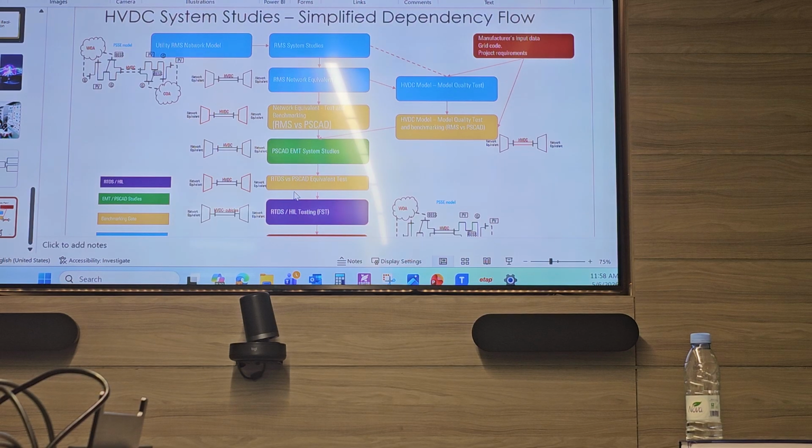But what I mentioned in the beginning is that before, with very few HVDC links and renewables, it was easily a big issue. But now you have many other devices, and this makes the network weaker in terms of short circuit current contribution, because the renewables do not contribute like normal generation, so this makes your system more unstable.